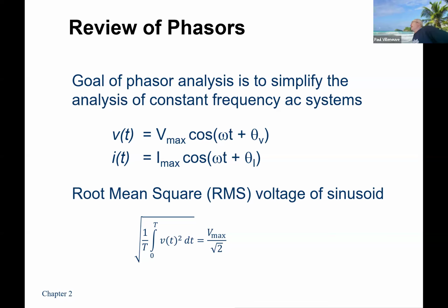So the term that I use, and maybe I wasn't as clear as I could be, is a sine wave, right? Very different than the sine of an angle. A sine wave is something that varies with respect to time. And a pure sine wave has no DC offset, really smooth. And mathematically, we can represent that as either a sine wave or a cosine wave, right? A sine wave is just a cosine wave that is phase shifted by 90 degrees. So hopefully you feel comfortable with either one of those representations.